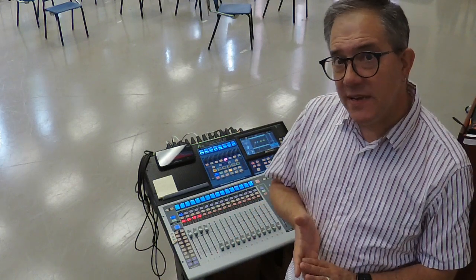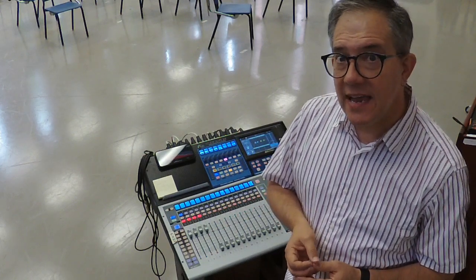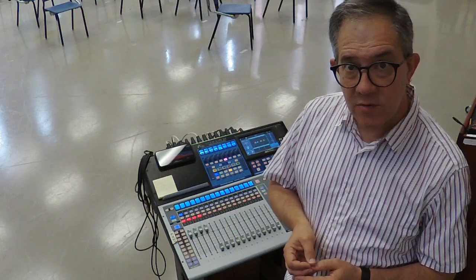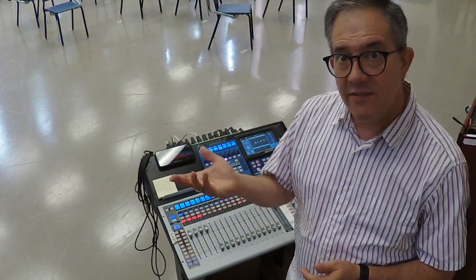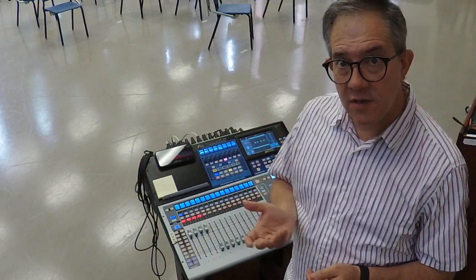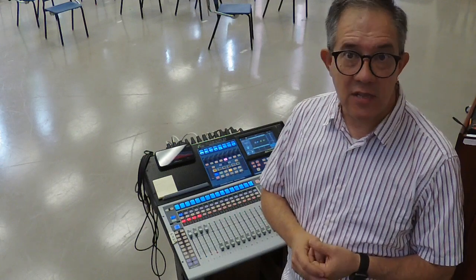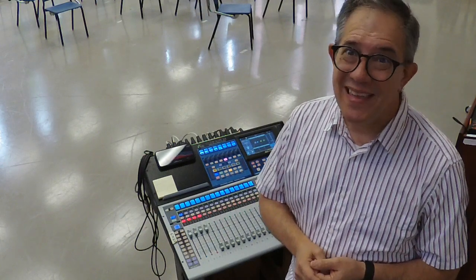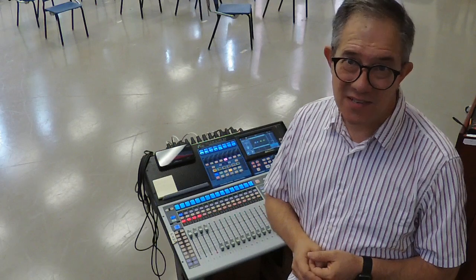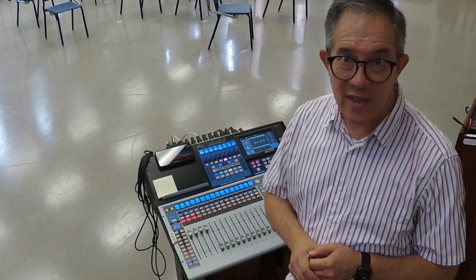Things that will exacerbate feedback have to do with less expensive equipment. Inexpensive microphones and speakers tend to have not as flat a frequency response. And if I have a set of microphones that happen to emphasize 400 hertz, which if you have multiple SM58s or multiple Sennheiser E835s in your church, it is emphasizing 400 hertz. It is what dynamic microphones do. It is part of the physics of the way they work.